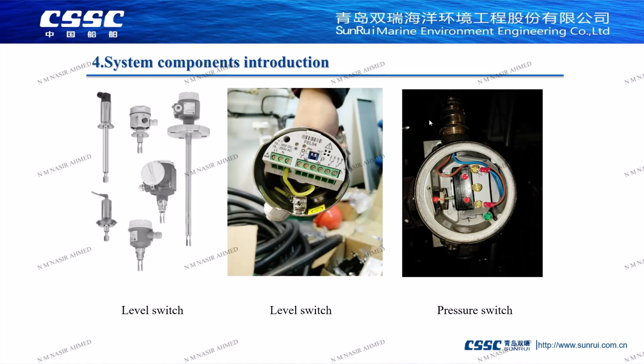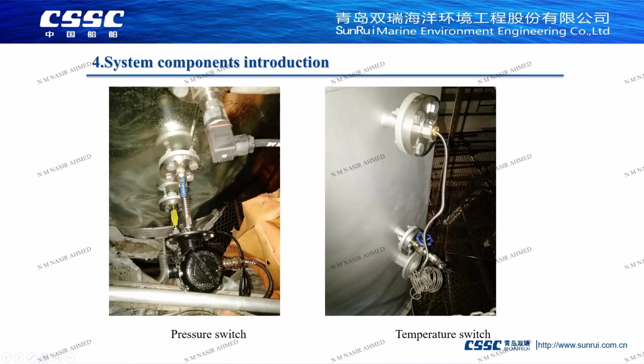The flue gas enters the desulfurization tower, and when the pressure is too high, it indicates that the pressure inside the desulfurization tower is obstructing smoke exhaust. The pressure switch triggers a hardware scram. The exhaust gas is bypassed directly when the system is shut down. The flue gas will no longer enter the desulfurization tower.